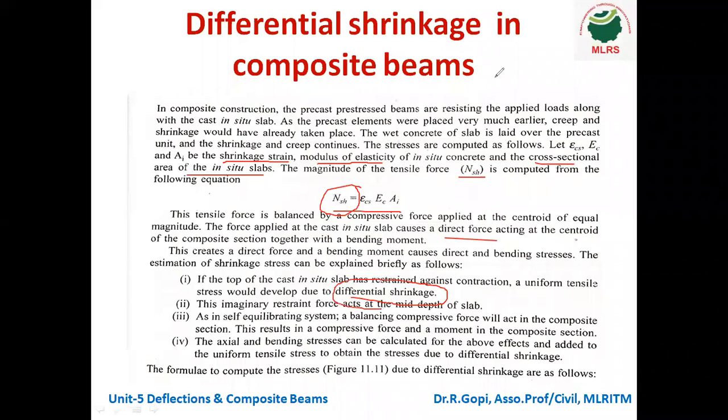Next, this imaginary restraining force acts at the mid depth of the slab, as in a self-equilibrating system. Equilibrating is nothing but equilibrium. Under equilibrium conditions, a balancing compressive force will act on the composite section. This results in a compressive force and a moment in the composite action.